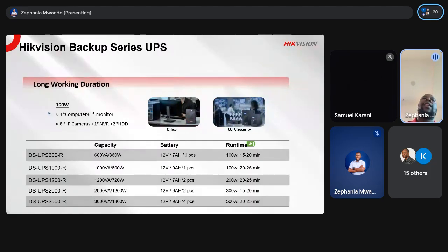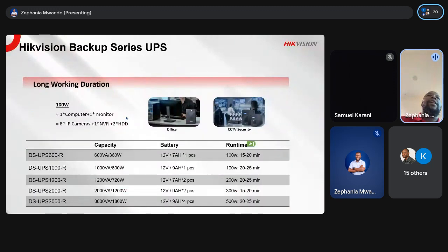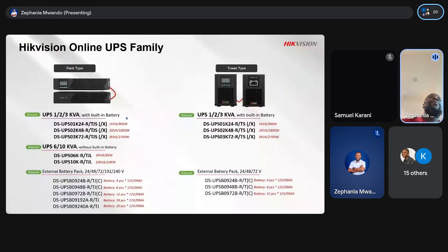Then in terms of calculations, you can always compare. Remember, a UPS is a transition device that would help you when power goes out, so you still have your equipment running and you restore a backup power supply. It's not the main backup source. So you can consider this in your deployments. So let's say you have a generator, you go for that. Then you have rack mount, let me say the online UPS. So we have the traditional UPS and also the online UPS.